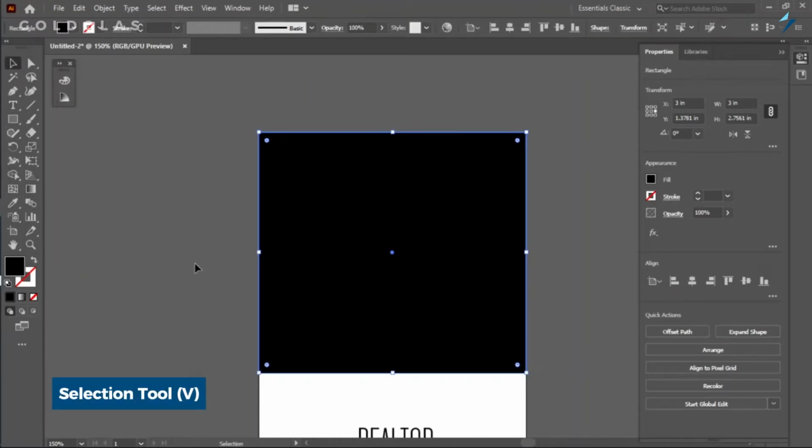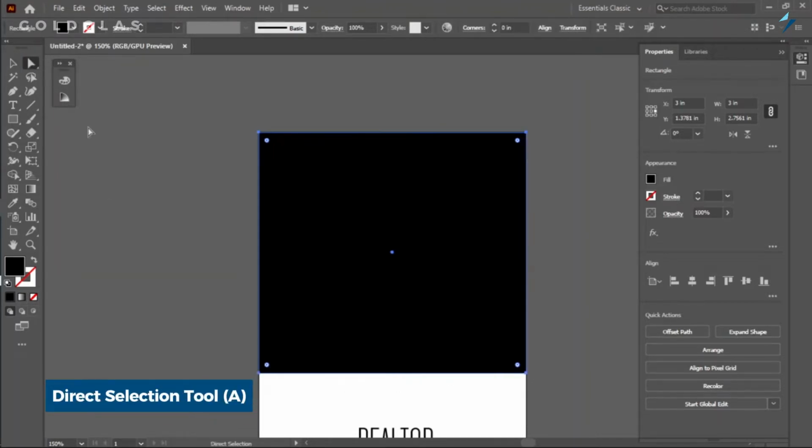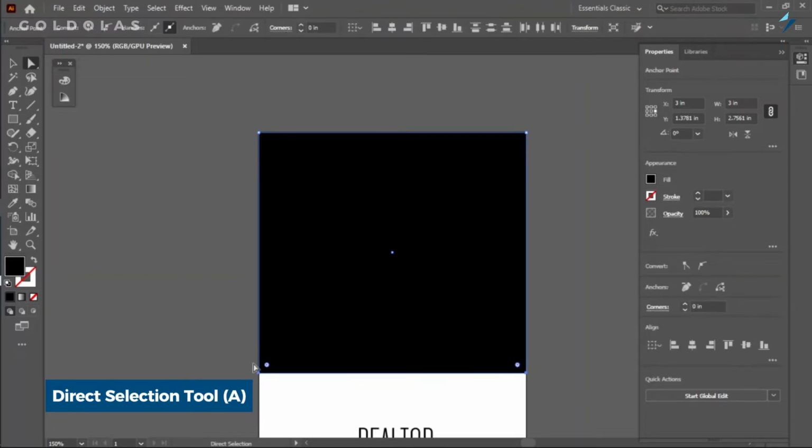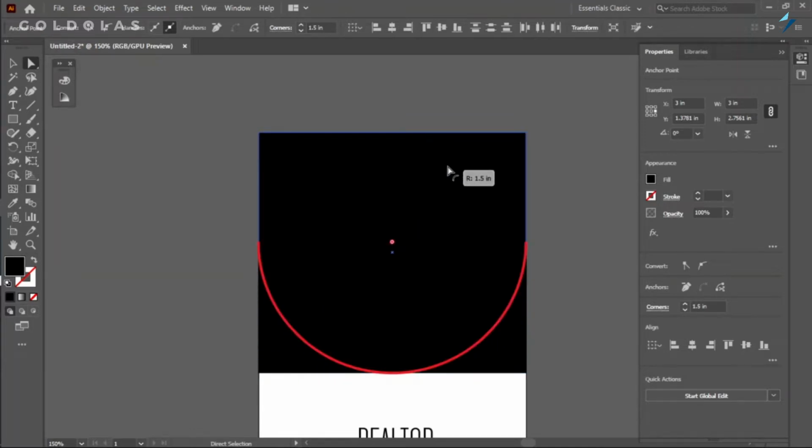So let me change selection tool. So I want to curve this part. Then come here, go to the direct selection tool. Click and drag. Then it's showing these 2 nodes, so you can increase the corner radius, increasing to the fullest. Yeah, so you have it like this.